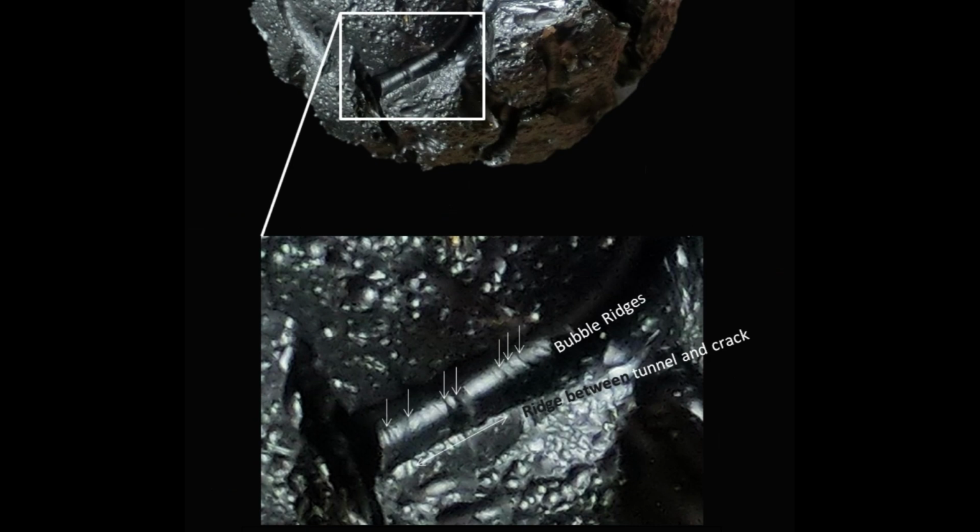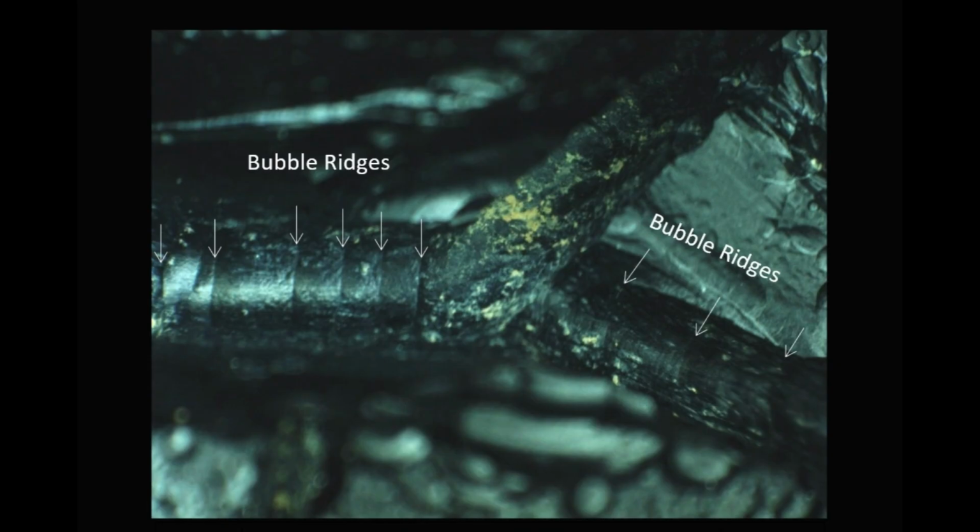The grooves themselves show three distinct features: bubble ridges, tunnel ridges, and Schlieren. Bubble ridges are sharp-edged and formed across the groove. Tunnel ridges formed along the grooves where the tunnel opened, between the shells. The tunnels combined mostly in three-way junctions.